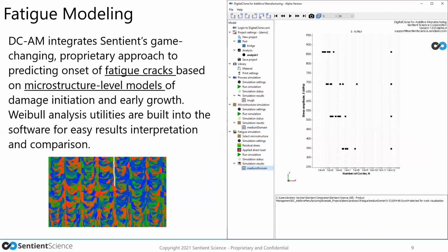Third, in the performance modeling, now that we have the microstructure, how will cracks initiate and propagate, and what will be the impact to the life of the part? The ultimate goal is to make sure that the additively manufactured part will satisfy the performance requirements. Starting with the part and its load analysis, we add in the microstructure, apply a load, and run the model to see how the crack would start and propagate until failure.